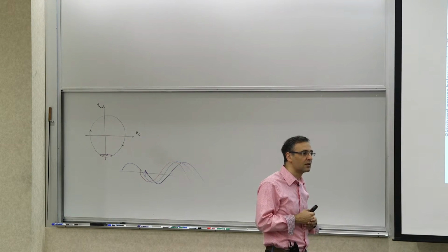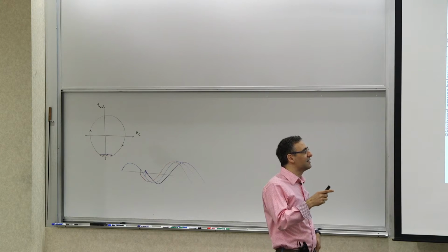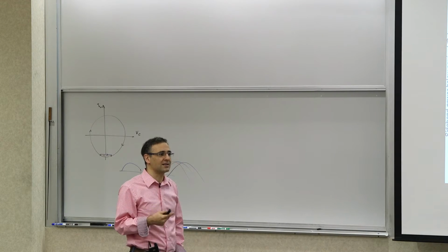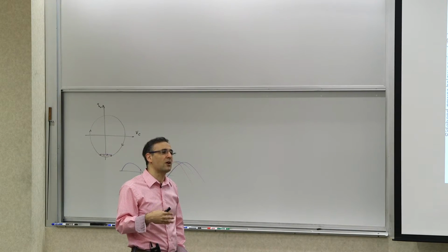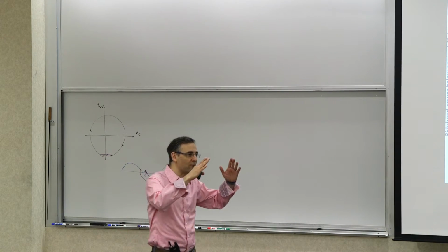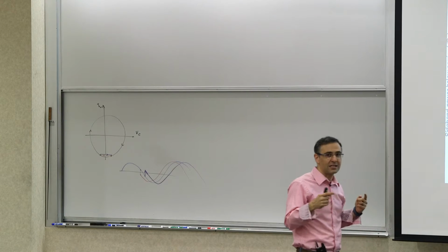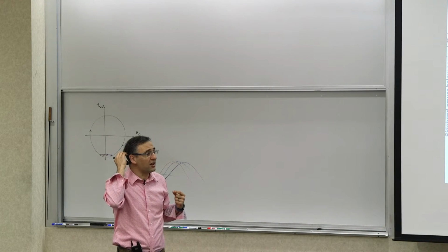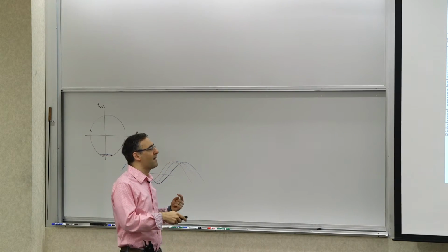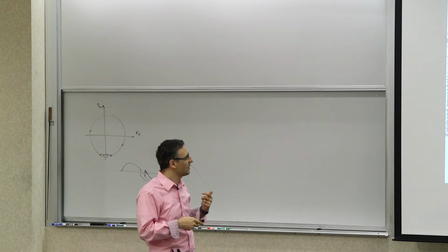Does minimizing mean, so whenever I see a plot like this and I see a minimum, that means that's a symmetric point? Well, it's symmetric as far as the upconversion. That's a good question. So the question is that this is the point where you minimize the value of C naught. So it's symmetric as far as it's optimum in terms of upconversion of noise. It doesn't necessarily mean that the waveform will look the most symmetric. It means that in aggregate, its effect is more symmetric. And that's a great question because it actually may not happen at exactly the point you may expect it, because also there are nonlinear capacitors and things of that sort involved. But the metric that you should be really looking at is minimizing the C naught, which is shown here.